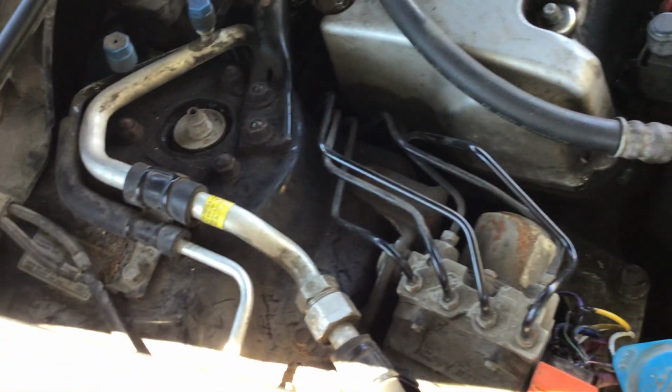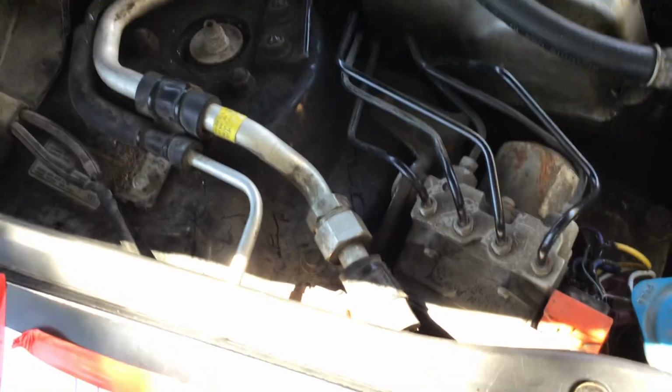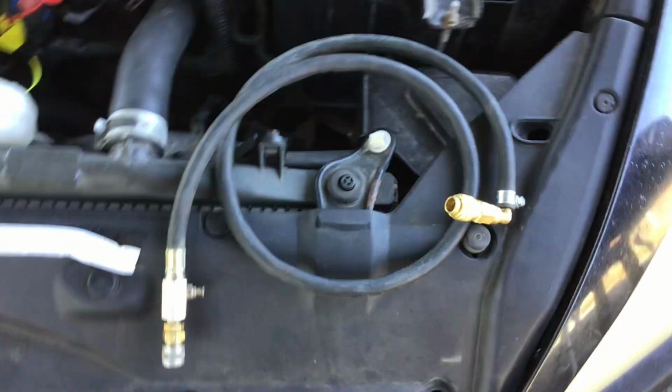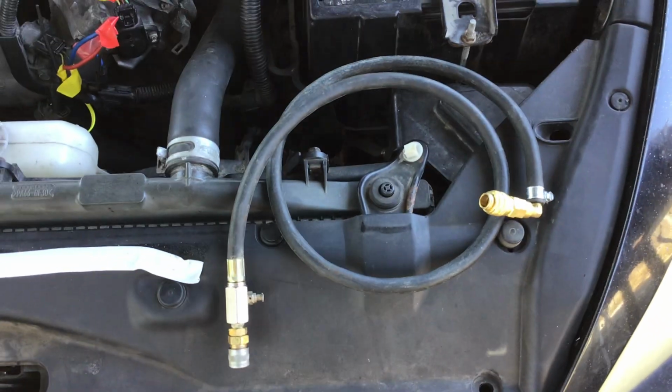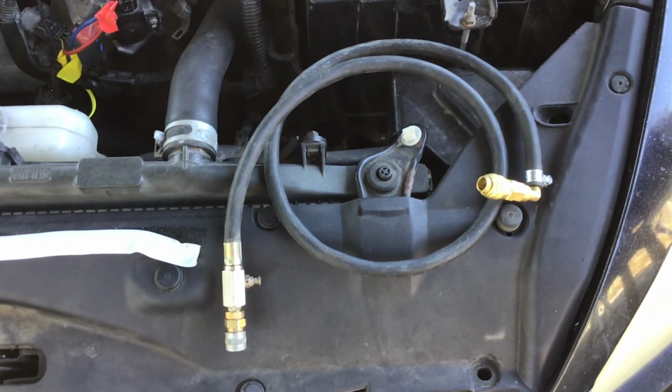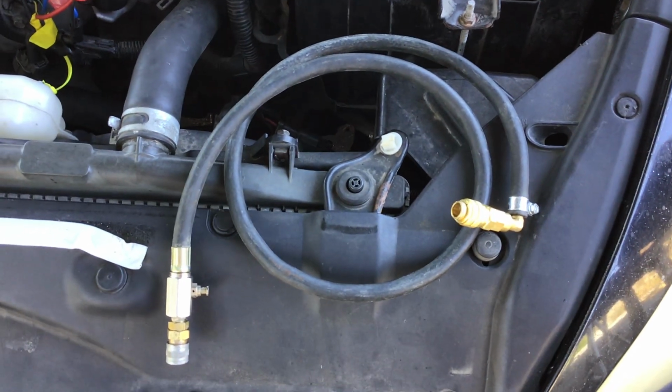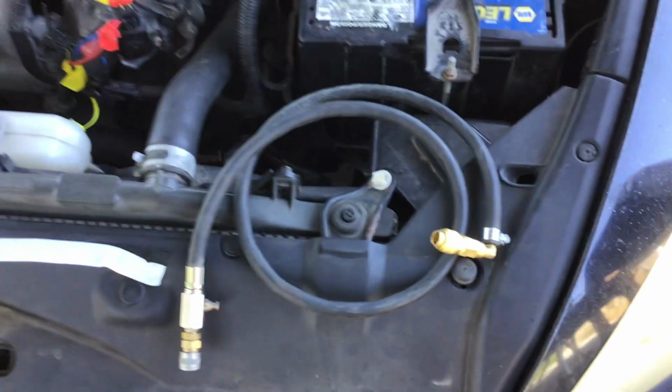I did make sure the hood was able to close without affecting the transducer, and then the routing of the oil hose. Be real mindful when you set this up. Don't do it hastily. Look for any rotating components to make sure they don't hit it. Any rub spots, nothing will hurt that.